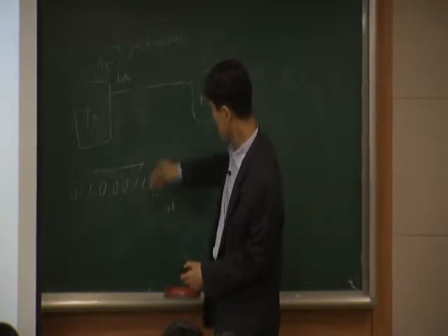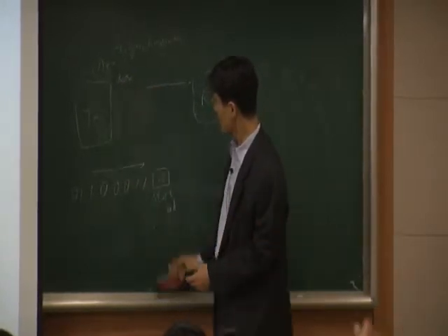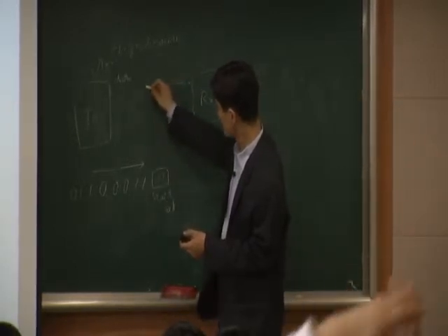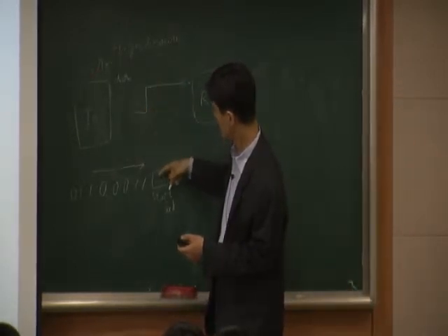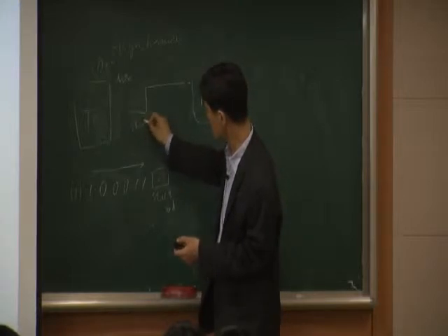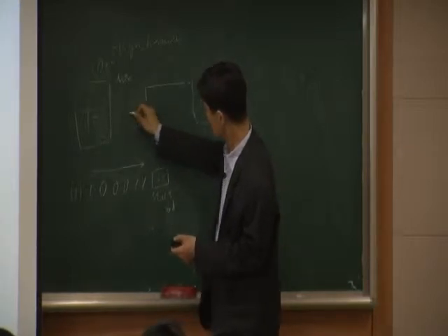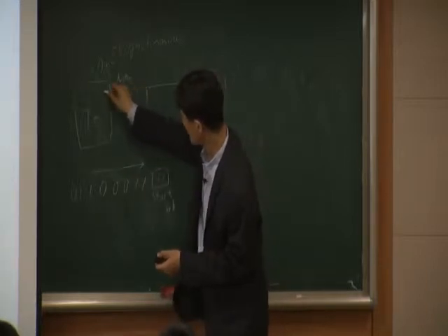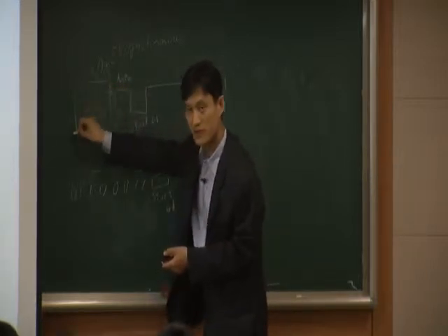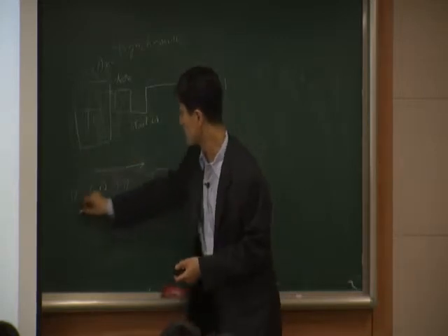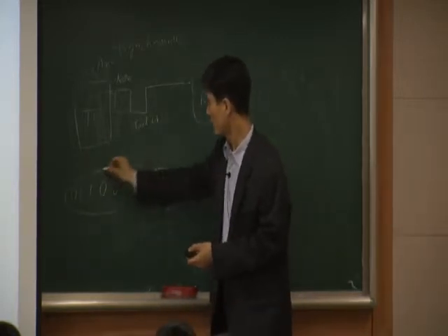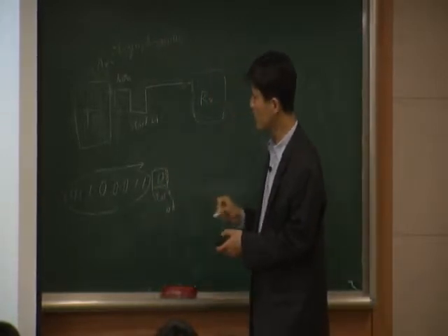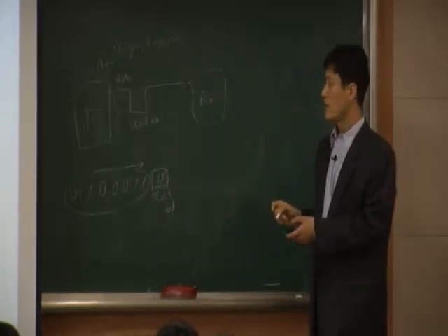Therefore, in idle state, this is 5 volts, but suddenly it goes down to 0 because of the start bit. We have a start bit, and then followed by 1100. It's 5, 5, 0, 0, something like this, right? So these 8 bits have to be preceded by 0. So 0 has to come first.